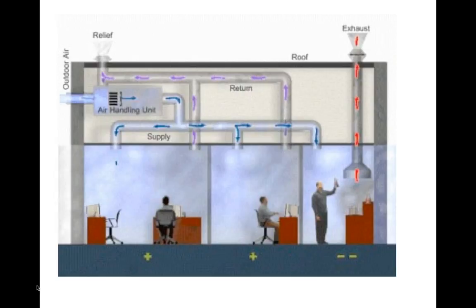So you see one illustrated here. When we were in the lab, we could see the diffusers delivering air into our space from an air handling unit. That air handling unit in the wintertime has coils in it that run steam or hot water through them so they can heat the air so that it reaches our space warm. Or in the summertime, they have coils that can cool the air. That can either be a refrigerant like Freon, or it can be cold water that's chilled by a device in a central plant and then piped over to that air handler.